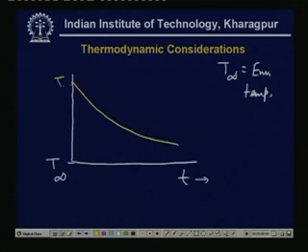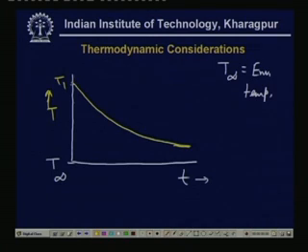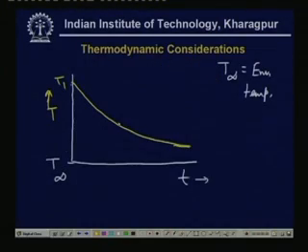So, this is T1 and we have measured T over here and it drops exponentially. Now, we see that once we give a heat input, that is once a braking operation is done, then the temperature goes high to a limit T1 and it drops down slowly depending upon various factors like U, A, M and Cp, and also the difference between the initial temperature of the body and the environmental temperature. Now, suppose after time T1 we apply another braking.